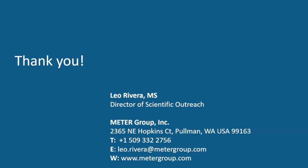Yeah, I think there's a couple things. One, it's important to know that if you're trying to do shallow measurements and you have a sensor whose field might actually extend into the air, you need to understand that when trying to do those shallow measurements. But also, if we're looking at 5 to 10 centimeters or 10 to 20 centimeters, and we have a sensor that's encompassing a pretty broad range of that, how much spacing do we really need to quantify soil moisture in the shallow layers?